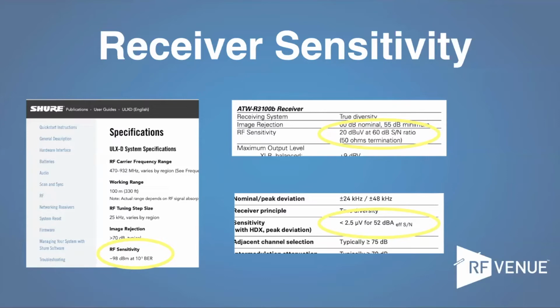But basically what the sensitivity means, this is the smallest signal that your radio can possibly tune in, get above the noise and work. I mean, you're right at the ragged edge. This is a very scary place to be. But this is the absolute drop dead minimum number under perfect no interference conditions that your radio could possibly work. You'll never be there, but there is a number. So you have to know that number. Your link budget always has to give you a number that's bigger than this.